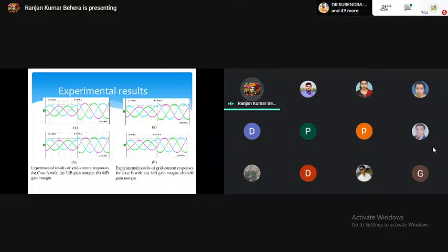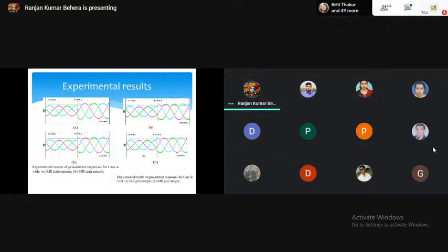But the most important thing is that with that quick response, there may be destabilization, because as soon as you jump, you may fall down. If you are stable, you can stay there, or else you can fall down. Like that, when you increase or decrease this bandwidth, the same effect is observed. When you decrease, the response is a little sluggish. When you increase, the response is very fast, but there may also be destabilization. You can see in these experimental results that at 3 dB there is a lot of ripple and it takes a lot of time.